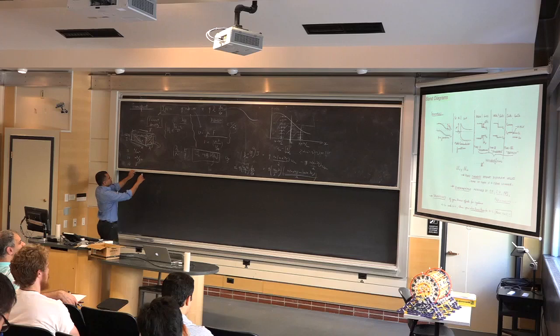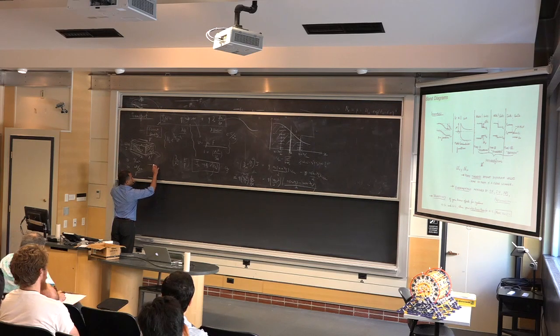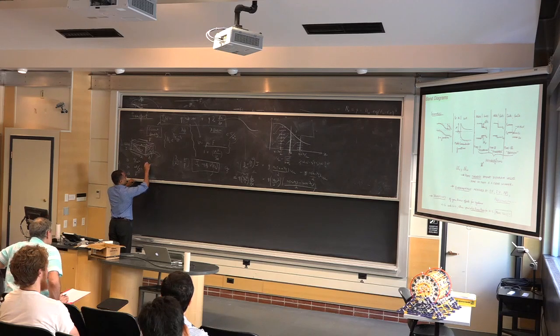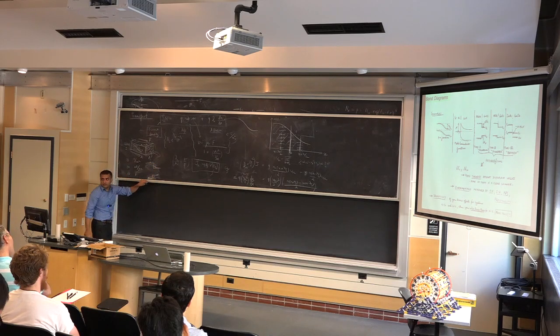One of the things you can see is if I took a junction, for example, instead of grading a band gap like that, you can take an abrupt junction like that, okay? And let's say you create electrons here and holes here. They will not stay there, right? Why? Because there's a lower energy available there. So the electrons will end up here, holes will end up here. This is just another way of saying that there's some sort of built-in quasi-electric field that's pushing both electrons and holes into the same direction.